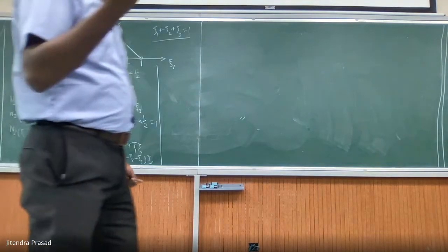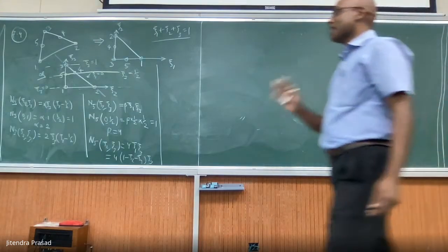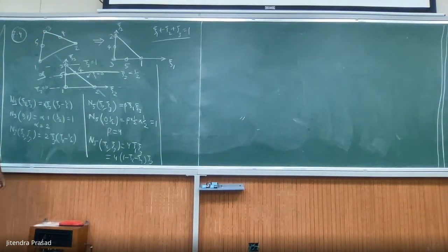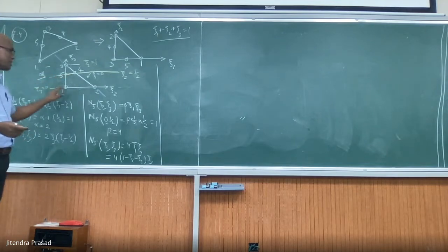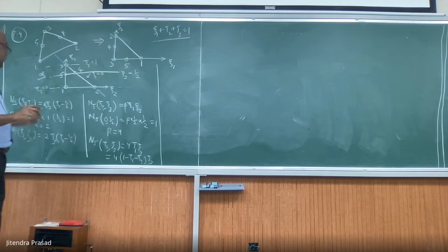So basically, it's 0 everywhere. It's constantly 0 only, meaning that it's linear. It falls in the definition of linear also. Right? So as such, this has to be 0 anyway. A shape function has to be 0 at all other corresponding points, right? So it will be 0 anyway. The only thing we have to check is that it is not quadratic. It's linear is okay, it's 0 is okay, but it should not be quadratic. So far it is not.